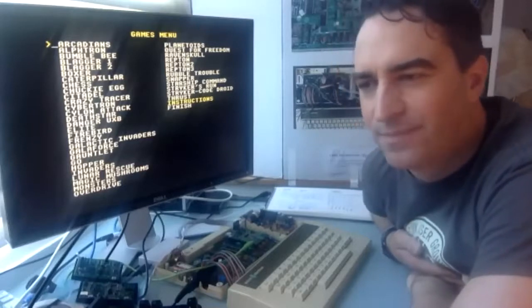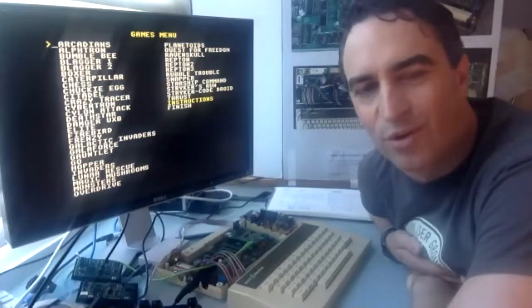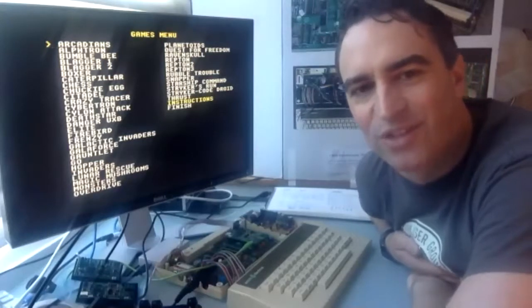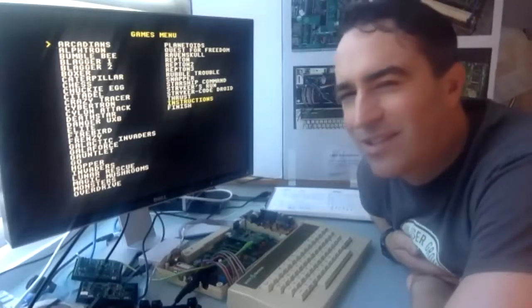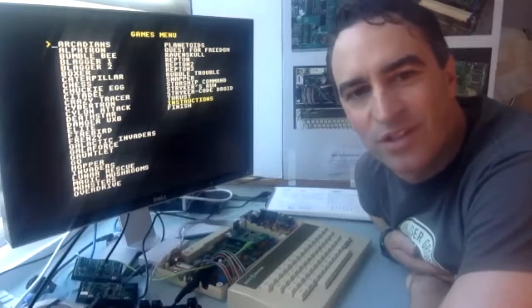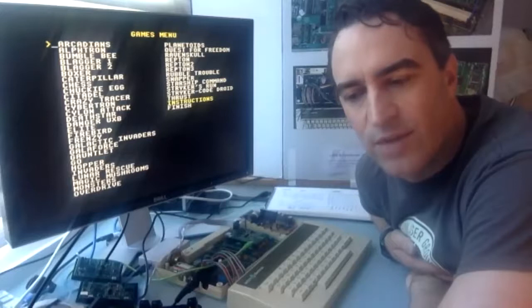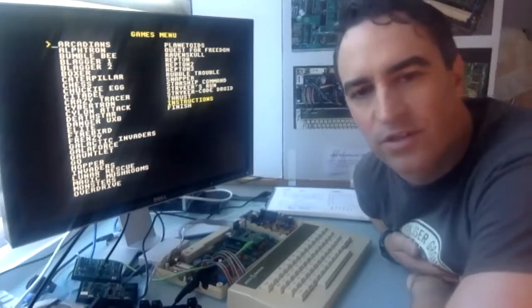So I have the undesirable choice of either porting everything to Verilog or trying to expand Icarus Verilog's VHDL support. I think maybe I can get away with the middle ground of simplifying some of the VHDL so it doesn't use any complicated features, and doing a little bit of hacking on Icarus Verilog's VHDL front end.